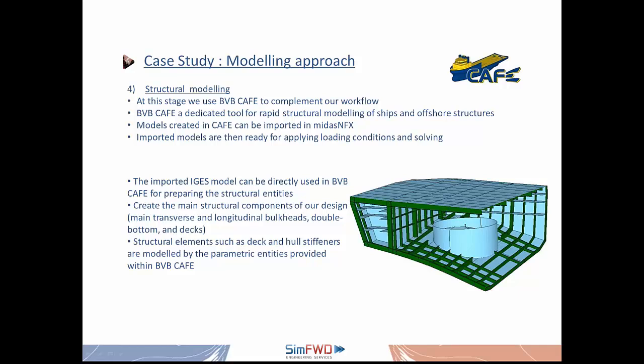So we are trying to find a workflow that is very convenient for modeling, meshing, and solving ship structural problems. BVB CAFE, in short, is a dedicated tool for rapid structural modeling of ships and offshore structures. We have been using the approach for quite a long time now, also for research and commercial projects.